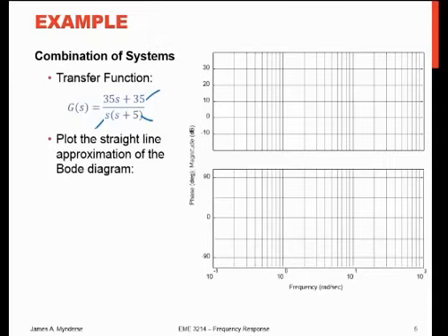So, basically, we know that our steady state gain, if we had a steady state gain, would be, what was it? I forgot already. 17 dB, which essentially means we could add 17 dB everywhere, from one side to the other. I could just draw a line here at 17, and that would be one of the things I would add in. Then that just ends up with too many lines. But what I'd also see here is a pole at 0, okay?